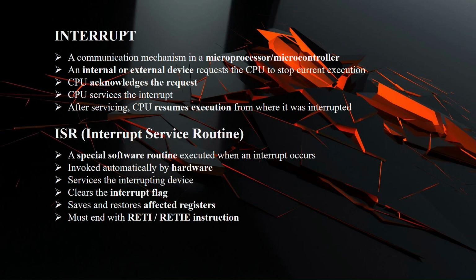Next is interrupt. An interrupt is a mechanism that allows a device to request immediate attention from the CPU. When an interrupt occurs, the CPU stops current execution and jumps to an interrupt service routine. After servicing, it resumes normal operation.